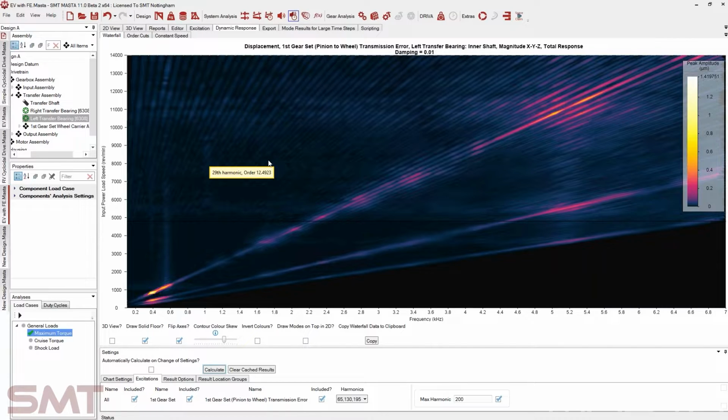And what you can see there is we're looking at exactly the same situation, but because we've looked at the entire rotation of that gear blank, we're now capturing that modulation information. We can see how the modulation has affected that response and how the sidebands have been produced.